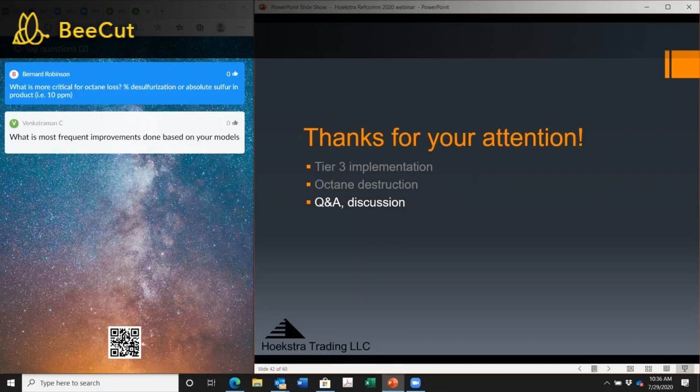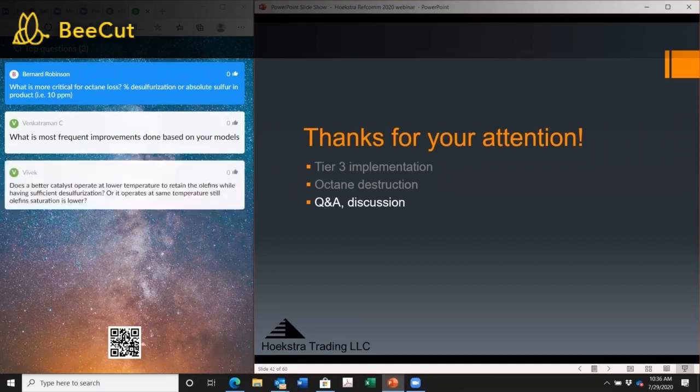We used to run in our cat cracker the pre-treated feed. So there was no need for us to do gasoline desulfurization. That's a post-treatment. We didn't have that. But all the FCCs are not like that. Mostly you're trying to feed the atmospheric residue, and so if you feed all kinds of junk into the cat cracker, the hydrotreating is a big challenge.